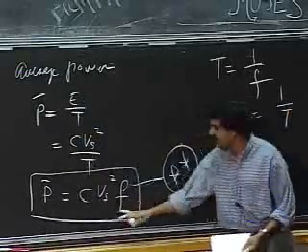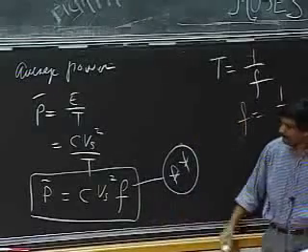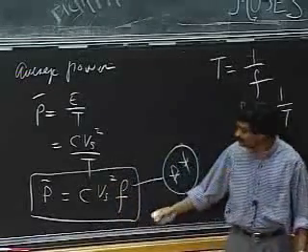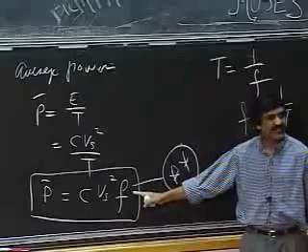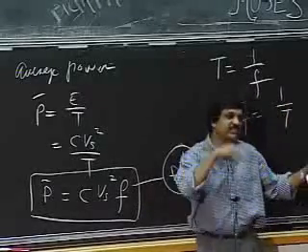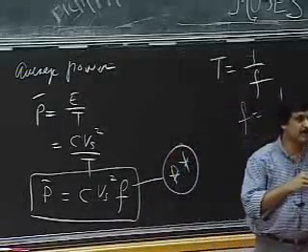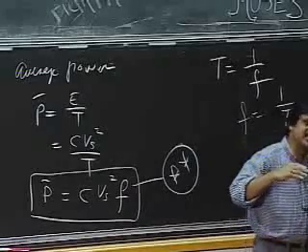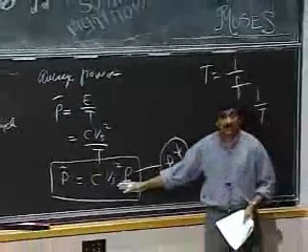So this average power is C Vs squared F. What this is saying is that if F is high, if I have a high frequency of charging and discharging the capacitor, then I'm charging and discharging much more frequently, so I'm going to consume more power.